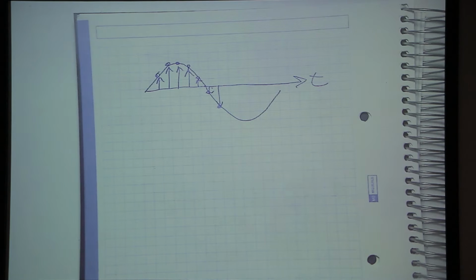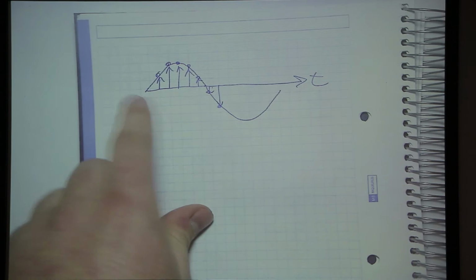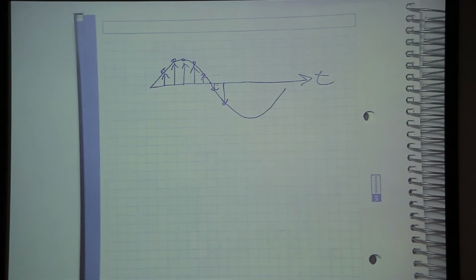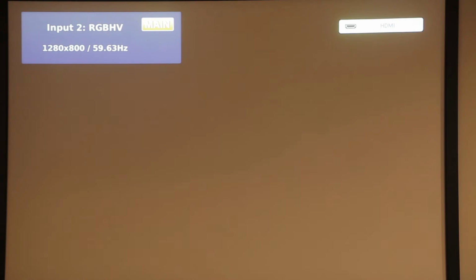And having recorded that, we can work out the frequency quite easily. Obviously, if this takes 10 cycles to complete and go back to 0 phase, then its frequency is 1/10, say, whatever that corresponds to. And if it takes twice as many samples, then it has half the frequency. So, in a sense, phase is the really important thing we want to actually measure here. Before I explain how we measure it, I thought I would have a quick demo of what this actually looks like with some real signals.